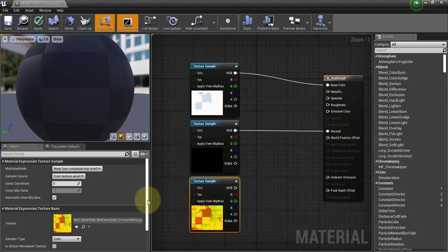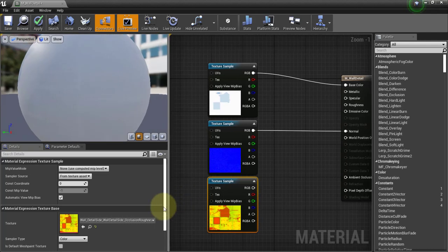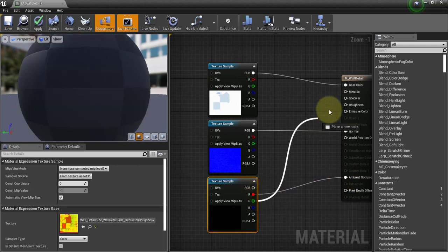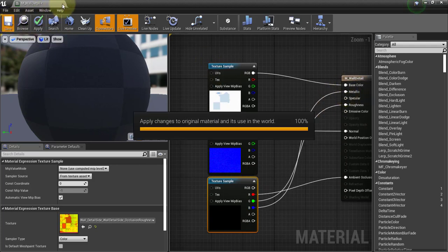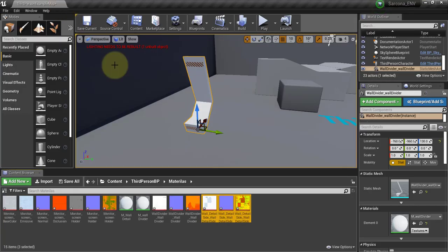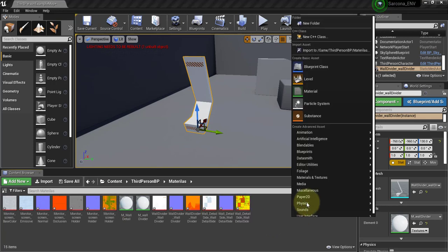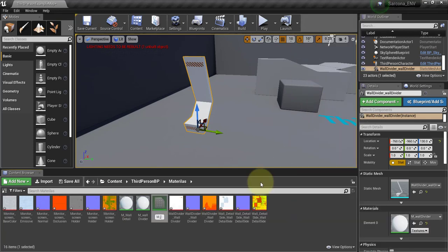And which one is this one? Yep, occlusion, roughness, metallic. Always that order. So red goes to occlusion, roughness, metallic. Hit save. Wait, and then we close. And then while I'm here, I'm just going to make 2 more materials, M underscore screen, and M underscore screen arm.